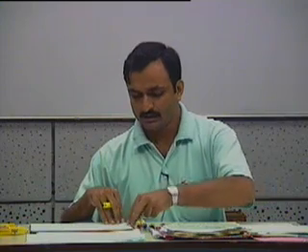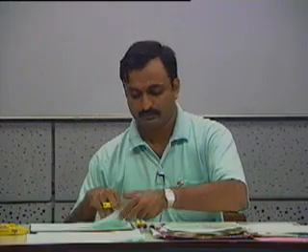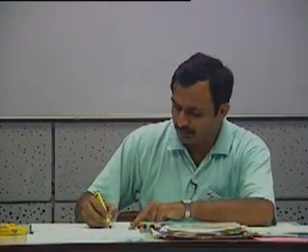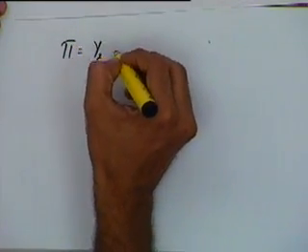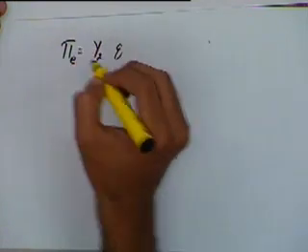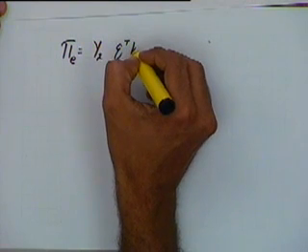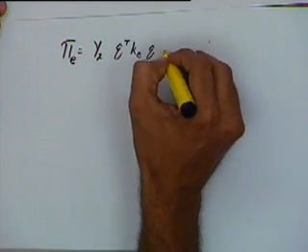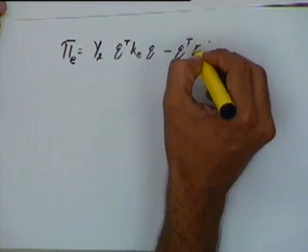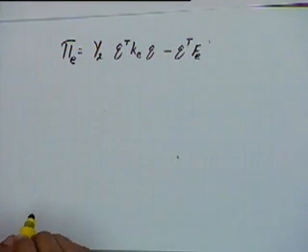Okay, so the potential energy of the element is given by pi, which is equal to half Q transpose KE multiplied by Q minus Q transpose FE. This is the energy of the element.